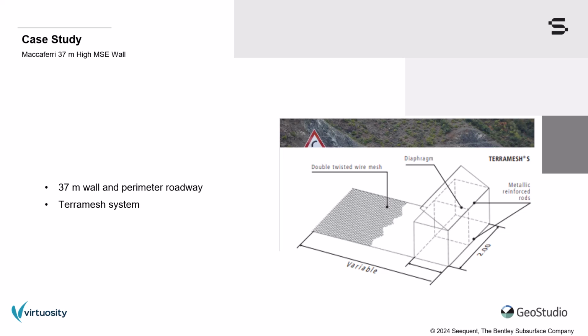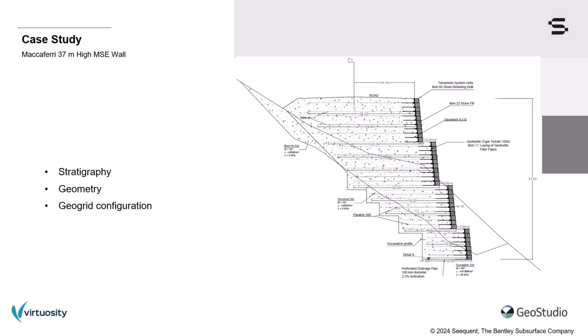The length of the base behind the gabion is project specified, and that's why it varies in this picture. The stratigraphy comprises a foundation soil, backfill material, and a structural soil which is used as a backfill behind the gabions. The MSE wall was constructed in 4 benches with batter walls having a face inclination of 5.7 degrees from vertical.